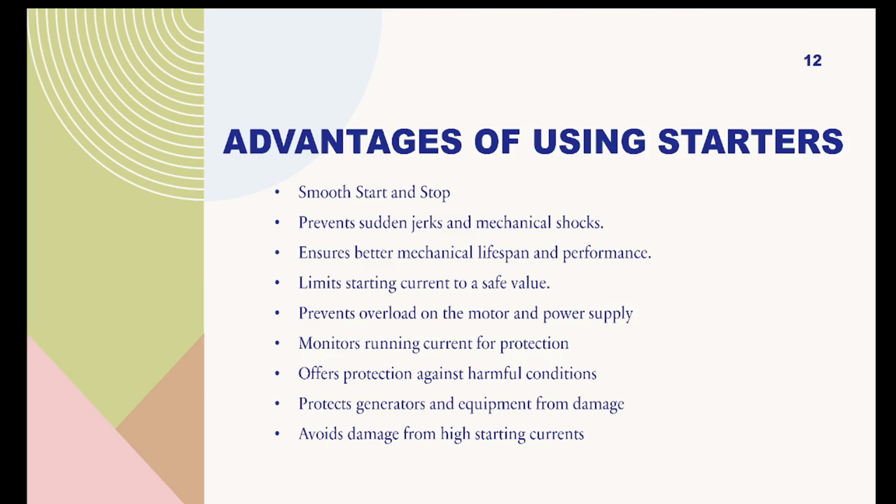Advantages of using starters. Smooth start and stop. Starters ensure that the motor starts and stops smoothly, preventing any sudden jerks or mechanical shocks. Limiting starting current. They limit the starting current to a safe value, preventing overload on the motor and the power supply. Protecting the motor and power supply. Starters monitor the motor's running current and offer protection against overload, undervoltage, and other harmful conditions. Safety for connected equipment. They also help protect generators and other equipment from being damaged by high starting currents.